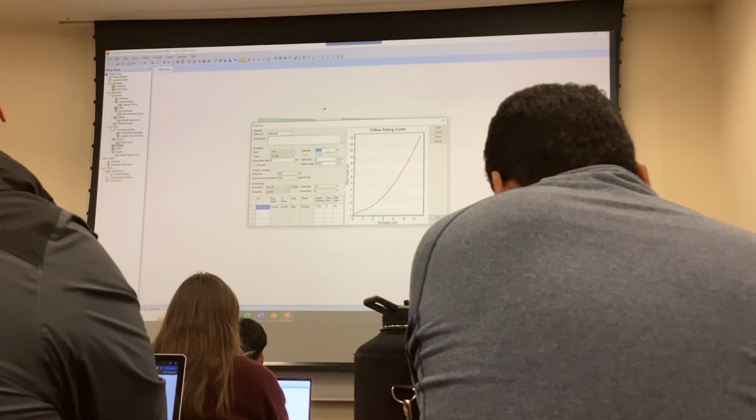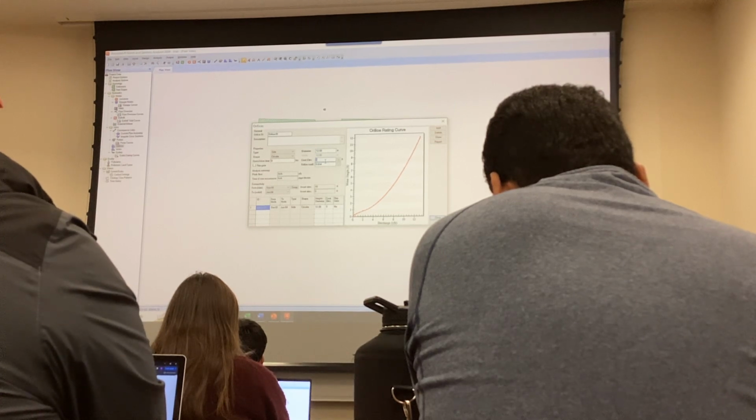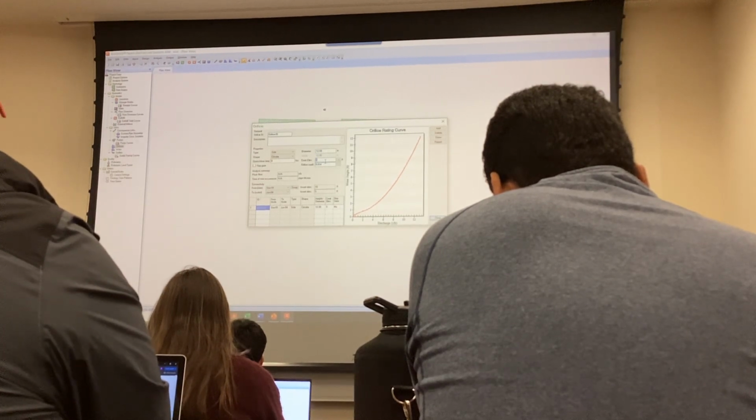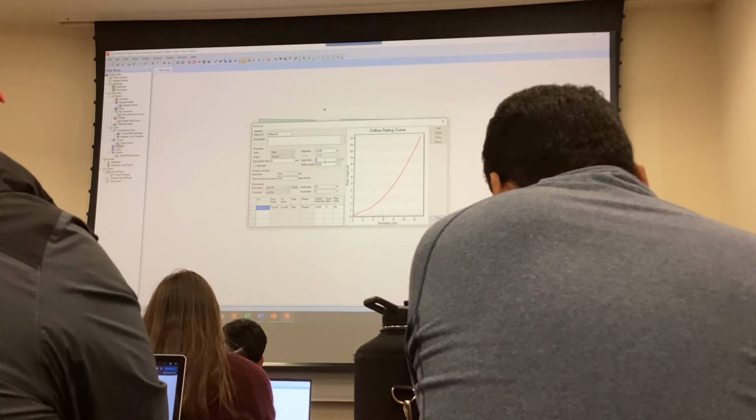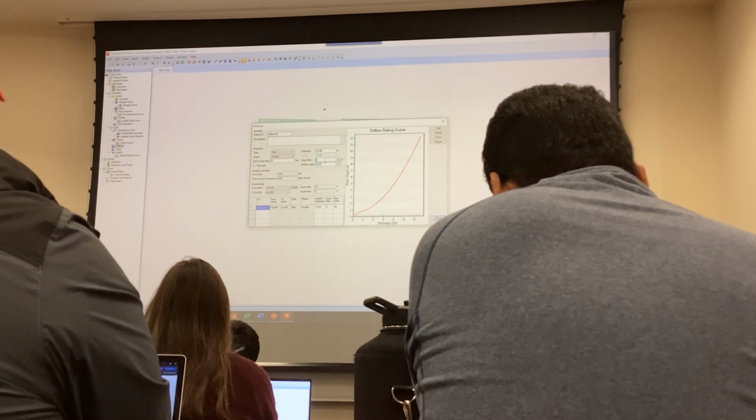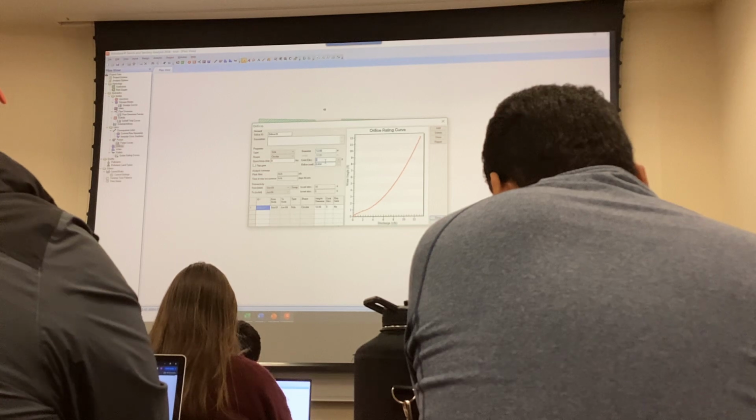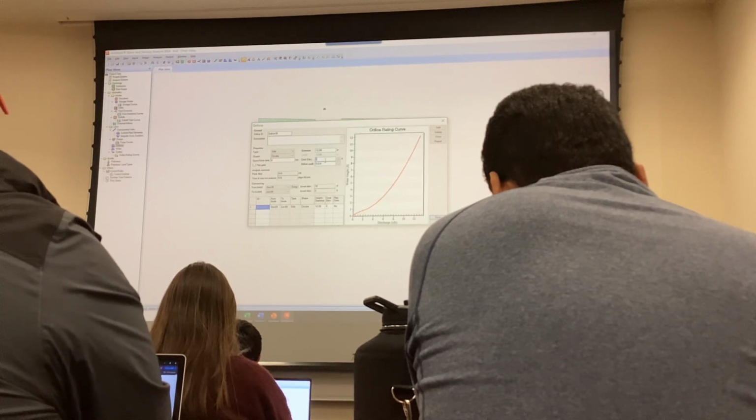So I'm going to let's say 12 inch diameter, and here's the different thing that we have versus what they have. They basically want you to specify the crest elevation instead of the center line, right? So if you know what the center line is and you know what the diameter of orifice you want, it's not very difficult for you to figure out what the crest elevation is. It's just adding the radius.